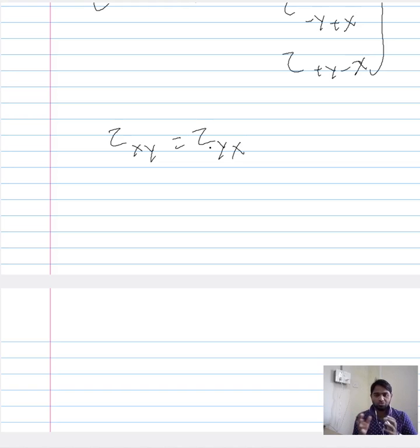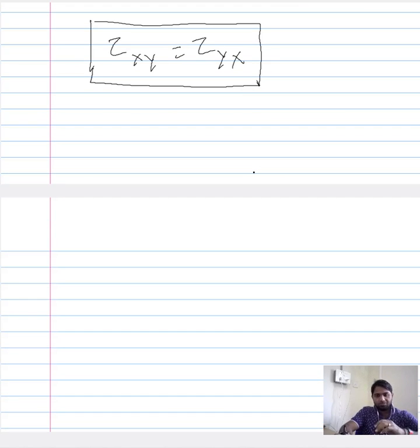We want to reduce it to independent components alone, and we saw that by virtue of the stress square, when you are talking about a fixed point, in order to maintain its rotational stability, this condition needs to be fulfilled. Now let us try to rewrite the components that we have already seen that are required to describe the mechanical condition experienced by a point in a three-dimensional setup when it is experiencing a triaxial loading.